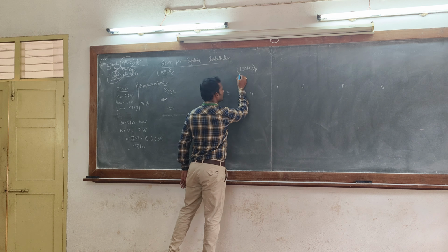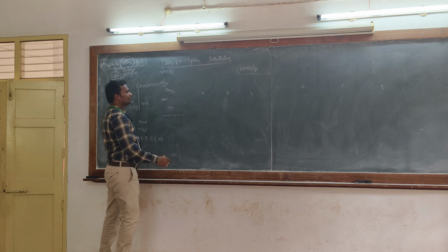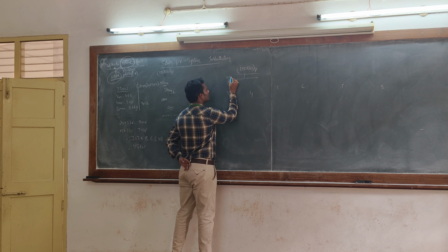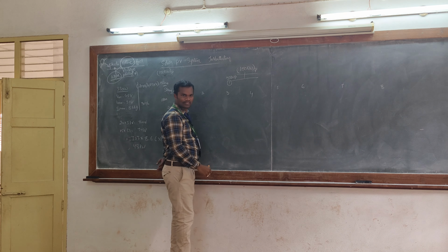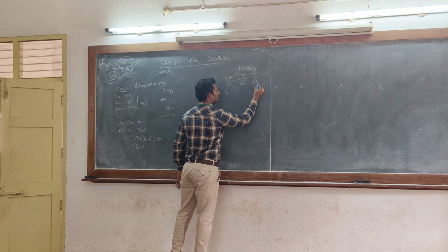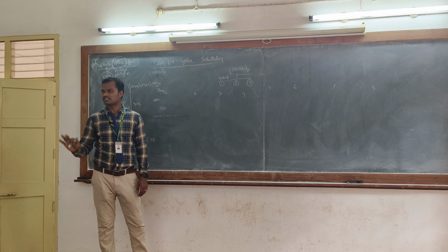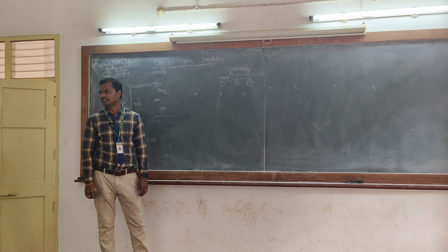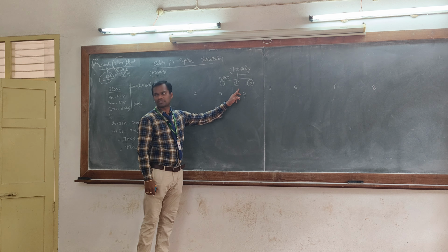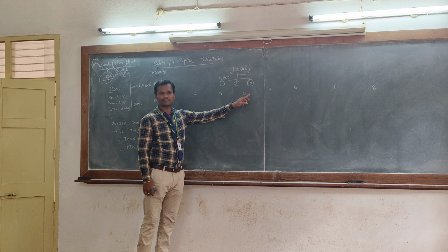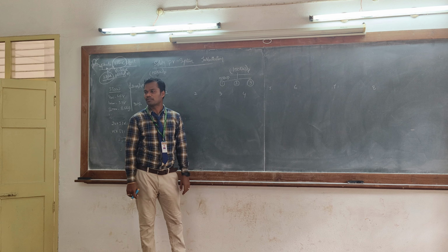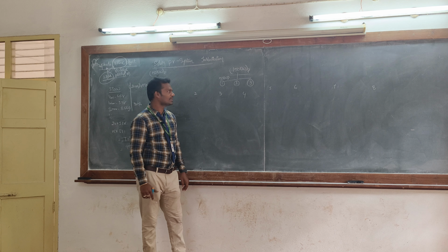This 150 kilowatt peak solar plant we are going to design in three segments, where the first segment is a 50 kilowatt peak grid connected inverter. Similarly, we have one more grid connected inverter, and one more after that. Like this, we have three grid connected inverters. Each is rated 50 kilowatt: 50 plus 50 is 100 kilowatt, 100 plus 50 is 150 kilowatt. So resultantly, we have a 150 kilowatt solar PV plant at the top of our building.